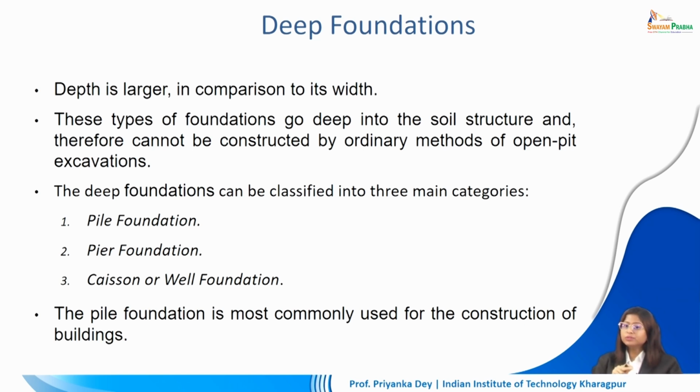Now, shallow foundations are different from deep foundations in another aspect, not just the depth. The second thing is, a shallow foundation is actually an open type of foundation, because there you have to dig a trench to create that type of foundation. But in this case, you don't need to do open excavation. Deep foundation is also different in that aspect.